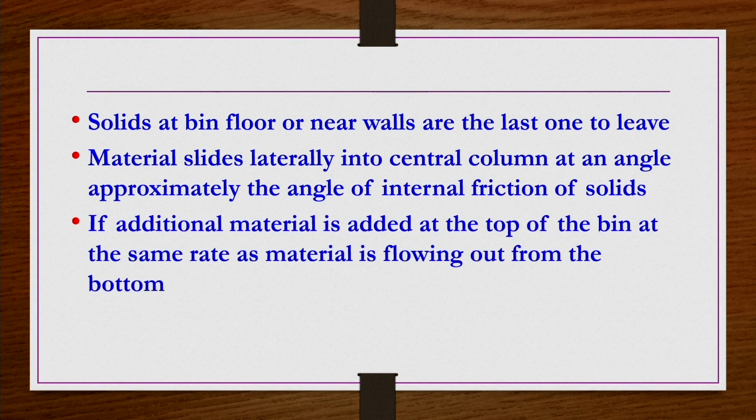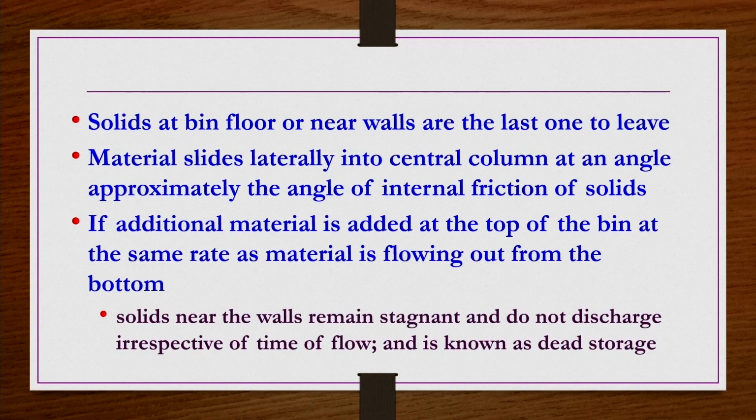As I mentioned, if additional material is added at the top of the bin at the same rate as material is flowing out from the bottom, then solids near the walls at the bottom remain stagnant and do not discharge irrespective of the time of flow. Whatever time of flow you allow, that material is not going to flow, and that is known as the dead capacity or dead storage.